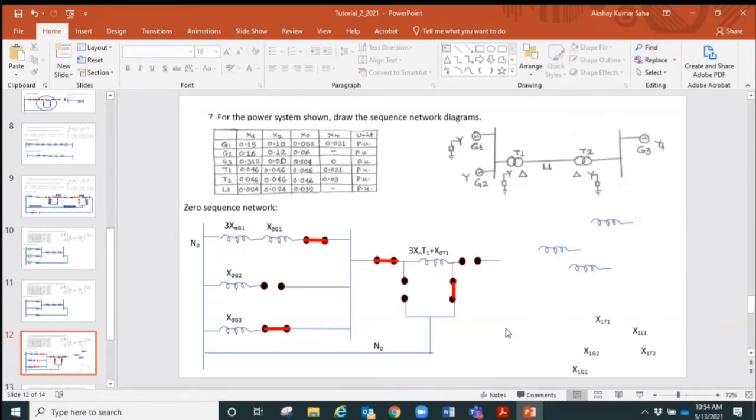So can you please explain a little bit how are we closing? Why are we closing the parts on the left and the right side of the transformer? If the winding is star connected grounded, then we close the series switch, the ones that you see horizontally at the moment. Okay. And if it is delta connected, then we close the shunt switch like this.